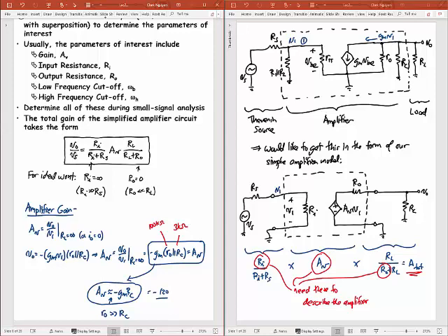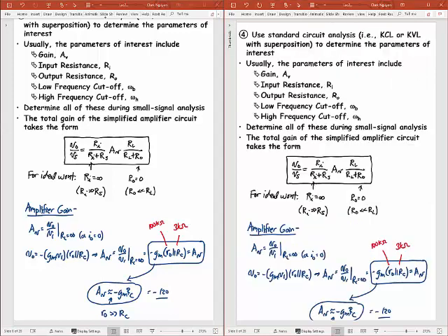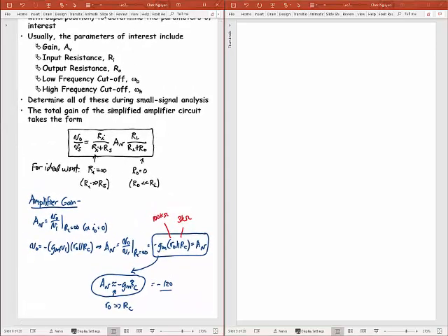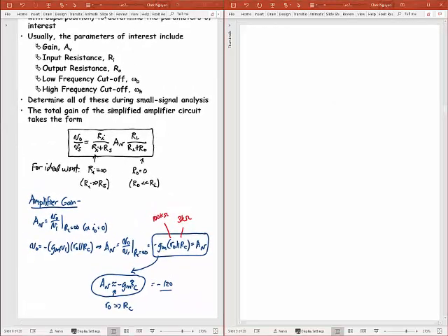of minus 120. Okay? Now, the other interesting thing to do, this is the actual gain of this circuit, but we should ponder what is the maximum gain that this circuit can give us. So say we had complete freedom of design. We can choose the R's to be anything we want to. What is the maximum gain? Well, the maximum gain then will occur when RC goes to infinity, right?